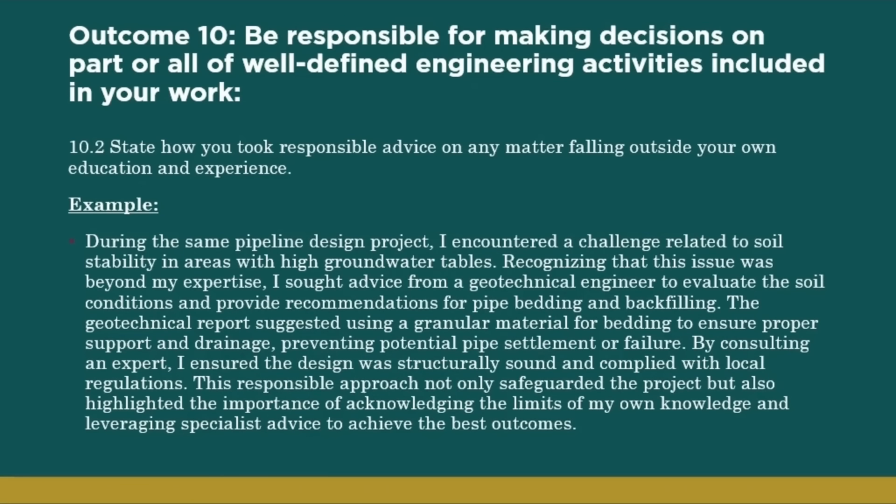The geotechnical report suggested using granular material for bedding to ensure proper support and drainage, preventing potential pipe settlement or failure. By consulting an expert, I ensured that the design was structurally sound and complied with local requirements. This responsible approach not only safeguarded the project, but also highlighted the importance of acknowledging the limit of my knowledge and leveraging specialized advice to achieve the best outcome.